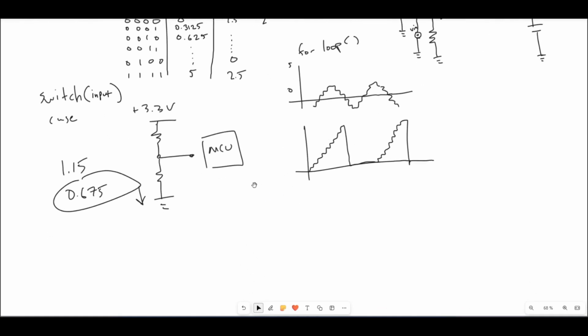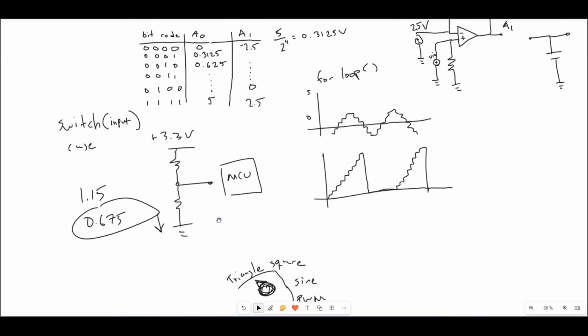And if you put that potentiometer on a PCB with some good masking, you could get an interesting setup here. Square, sine, PWM, let's just do that, for example. So you turn this pot here and it'll select. I think people even add a little arrow on your potentiometer, so you can select the waves like that. So that's one mechanism, where you could have a switch case running in your super loop. It checks the input in the beginning on the analog pin and finds what waveform it is.